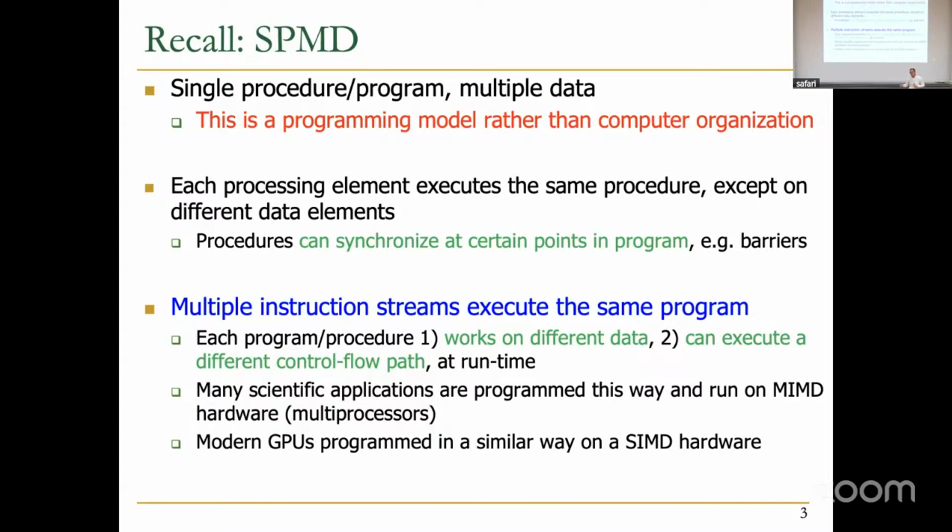in the sense that there are clearly graphics-oriented things that we didn't talk about inside the GPUs, like for textures, etc. There are specialized cores, special functional units for graphics computations. Those are not being used as much, but the general purpose cores that we've been discussing have become used by a lot of people. And GPU vendors also started making those more general purpose, easier to program, etc.